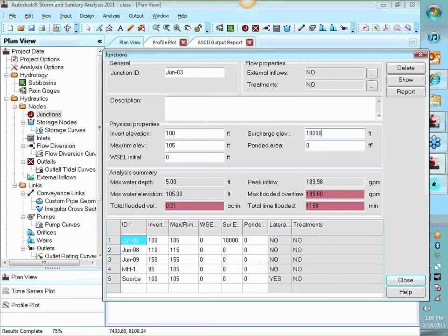So by restricting it, leaving that at 0, it means essentially the hydraulic grade line is set at the invert of the pipe. So when the pumps turn on, there's an immediate loss of water. So the rest of the system never sees any water. The pumps turn on, it goes into that first pipe, and it disappears because my surcharge elevation was 0,